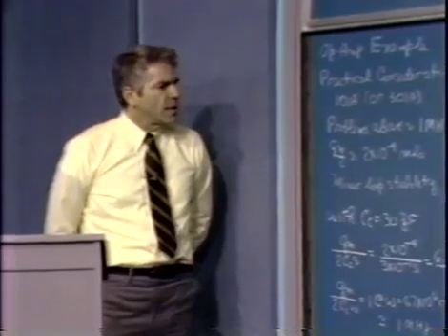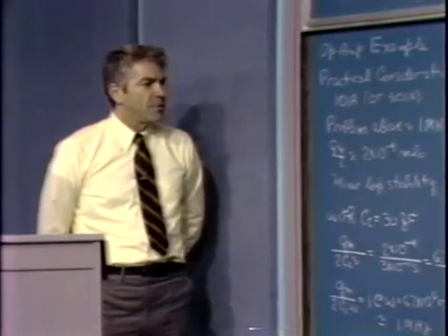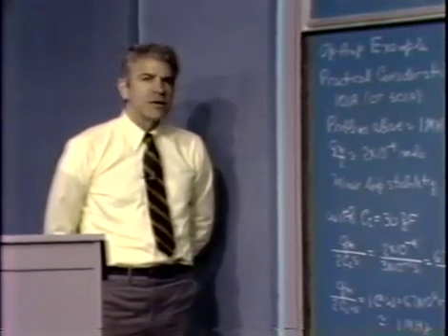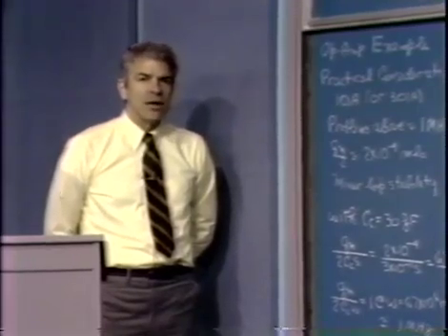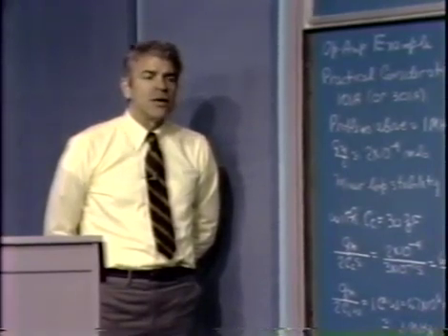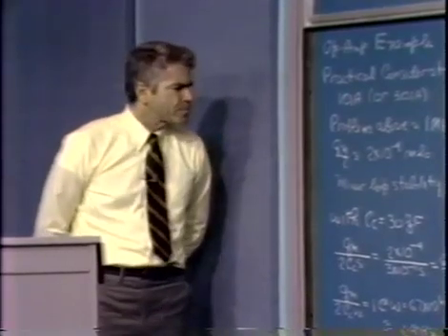So we have to bear in mind when we're doing our compensation that for any loop that includes this kind of amplifier, the major loop crossover is constrained to somewhere on the order of a megahertz. Actually, that's been getting a little bit better with time, reflecting process improvements. We'll see in the amplifier we're using now, we can get about 2 megahertz crossovers without too much trouble.